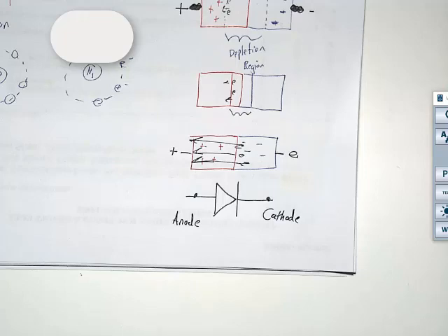We're no longer at the material. We are at a device. This thing is a p-n junction inside a nice plastic that's got little leads coming out of it that we can attach to. We're a diode. We want to be related to the concept of anion and cation, but we're not right at the silicon level. We're up a level, so we're going to differentiate ourselves by saying the anode and the cathode. Sound good? So when we talk about the diode, that's where that terminology comes from, okay?